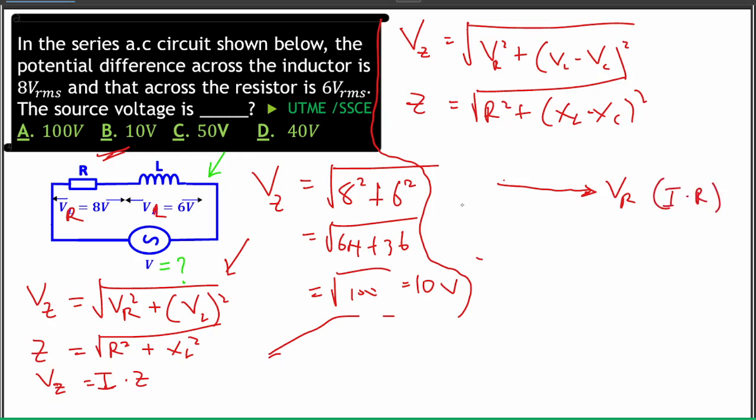Remember this. Okay, and then VL will be leading current. So we'll draw it like this, and then VC should be smaller, but it will be lagging current. Okay, so we have three vectors here to work with. How do we resolve the three of them? How do we find the resultant vector? You start with these two, the ones along the vertical, VL and VC. Since the angle between them is 180 degrees, or you say if two vectors are in the opposite direction, you just